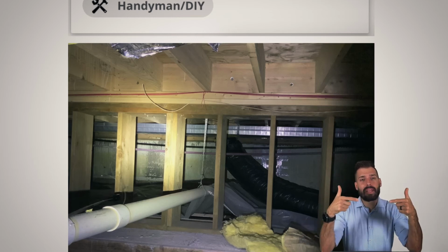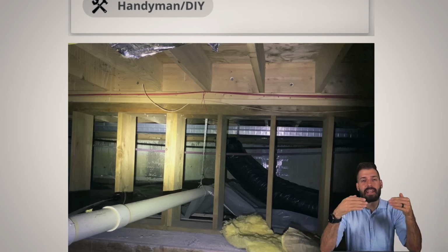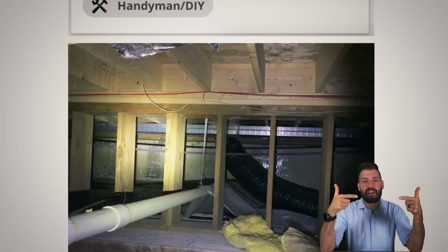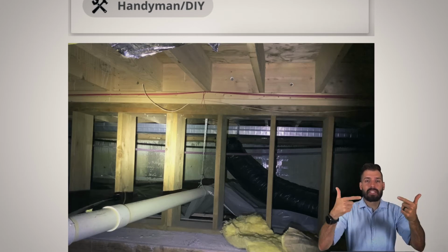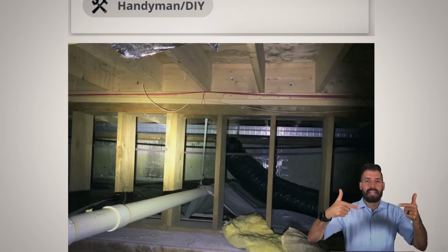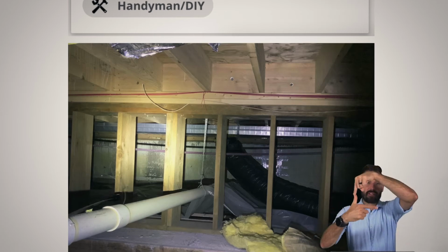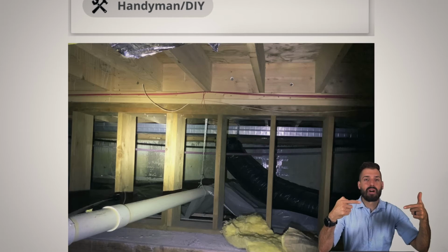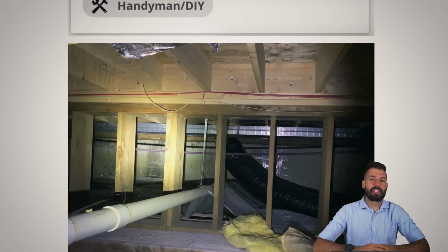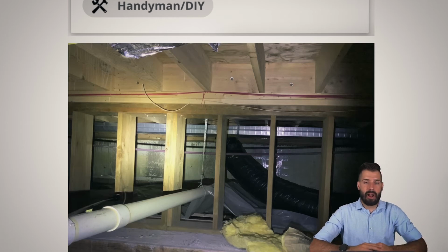And what you might notice is that the pipe can handle it. I know the pipe can handle it, but where the fittings are, each one of these fittings is rigid. And so what will happen is where the pipe actually makes its connection, that is where we are going to have a leak spring up. So we have 1, 2, 3, 4 different ways in which we can have this particular thing leak because we didn't have the pipe properly supported.